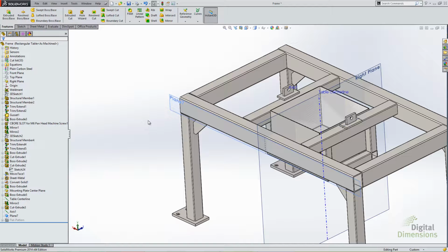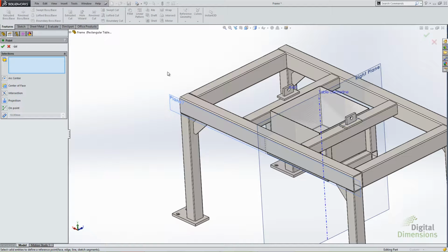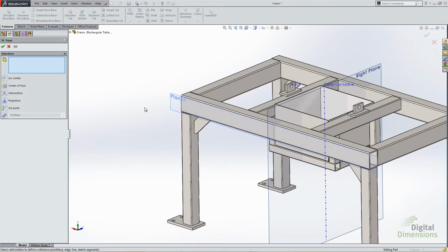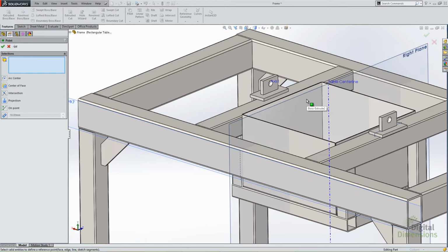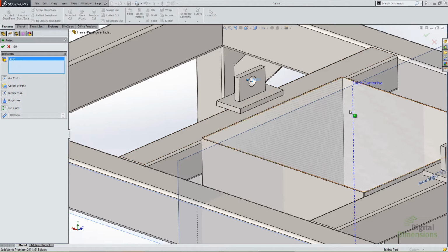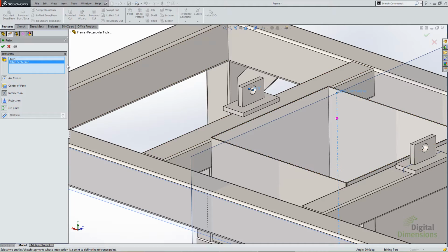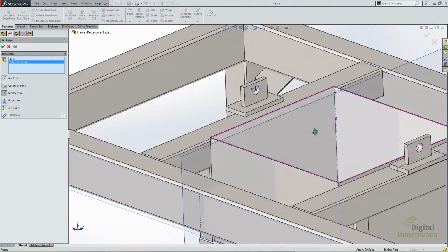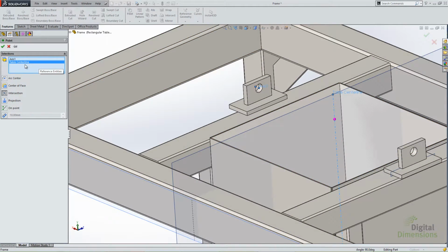Another enhancement to reference geometry is that of points. I'm going to go ahead and call up a point command. I want to point out a couple different scenarios for things we couldn't do in previous versions. There are some new selections that I can make and get points where in other scenarios I couldn't. The first is an axis and an axis. In previous releases we couldn't show the intersection of two axes, and now we can. If I select two axes, you'll see there my point.